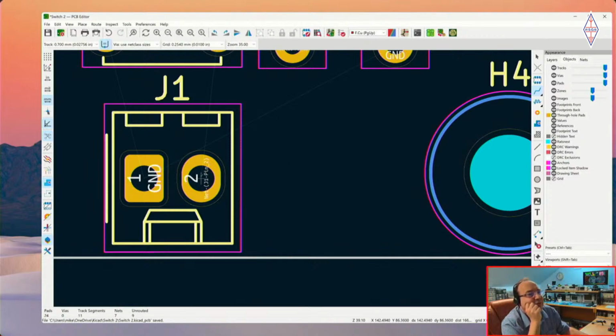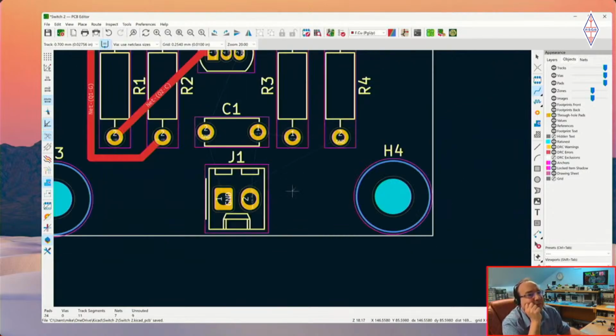So the step between component pins is typically 1/10 of an inch. This is going in about 1/50 of an inch at the moment. And you want it much finer just to ensure that you can align the tracks. Now, one thing you'll notice, by the way, is I'm not wiring up any of the grounds because I intended to use a ground plane on this board.